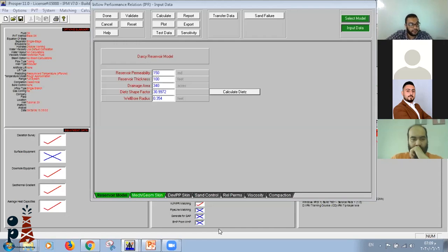There is another question from Abdullah Muhammad asking how skin can affect the flow regime. No, skin does not affect the flow regime. First of all, skin is along the interface with the reservoir. It's not across the VLP. It's at the completion, the intersection with the completion. Wait, I prefer to show it here.